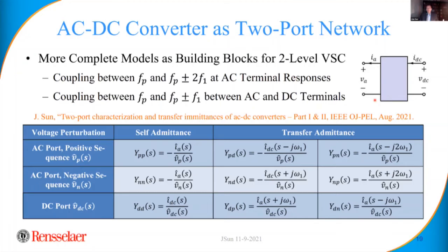And this 2-port network allows us to do that, particularly when you have to consider DC and AC systems together. Right? The converter couples them, and these transfer admittances allow us to model them together in one model. So we can use this model to study not just the AC grid, but also the hybrid AC and DC grid. A DC system is certainly simpler, because if you only have DC, then the linearization is much more straightforward. So we don't really have any difficulty. And so that's the latest development.